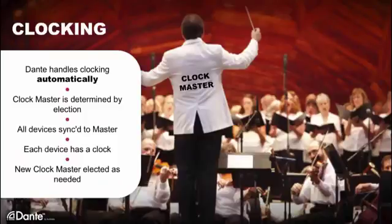When discussing digital audio fundamentals earlier, we talked about how important the word clock is. So, how does Dante handle clocking? While many adjustments are permitted, the important thing to know is that by default, Dante handles clocking 100% automatically. Dante uses an election process that chooses the best clock master among devices, and all devices on the network use that clock as a reference for synchronization. While a clock master is used to synchronize devices on the network, each Dante device incorporates its own high-quality clock. And by using this approach, jitter is eliminated as a problem on a Dante network, regardless of size.